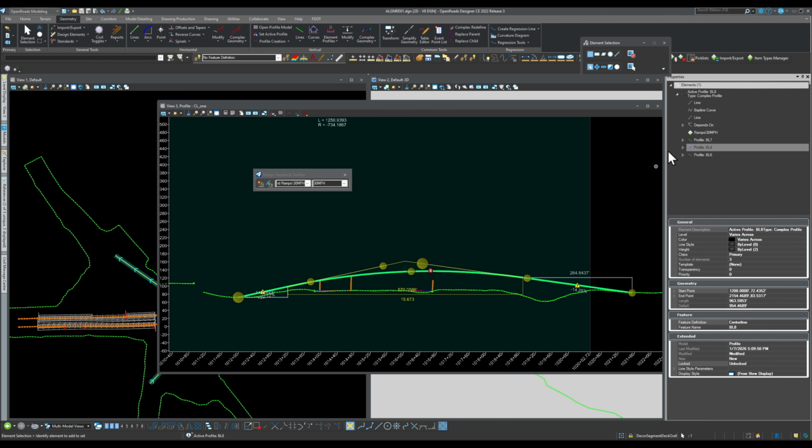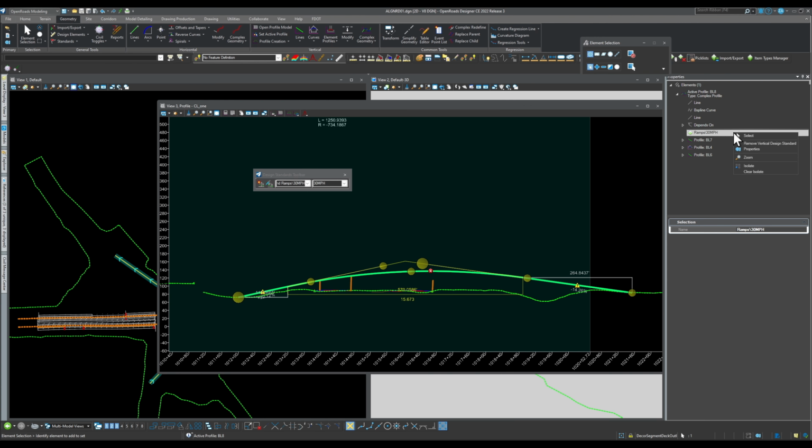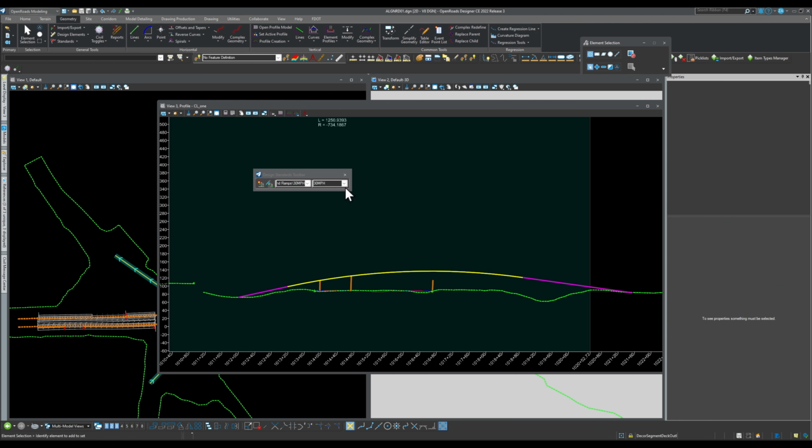Like I said, I recommend you add this to your work, just so you can check your work. And these here, the toolbar: first you select the category from here, whatever they have in your workspace. That's what FDOT has according to their design criteria. And then here is where you select your speeds. That's why they have two of them here. Okay, so now it's active, so let's save it.